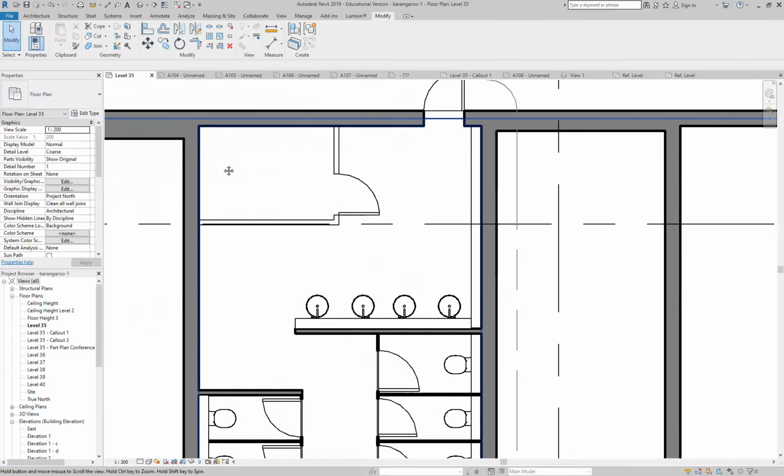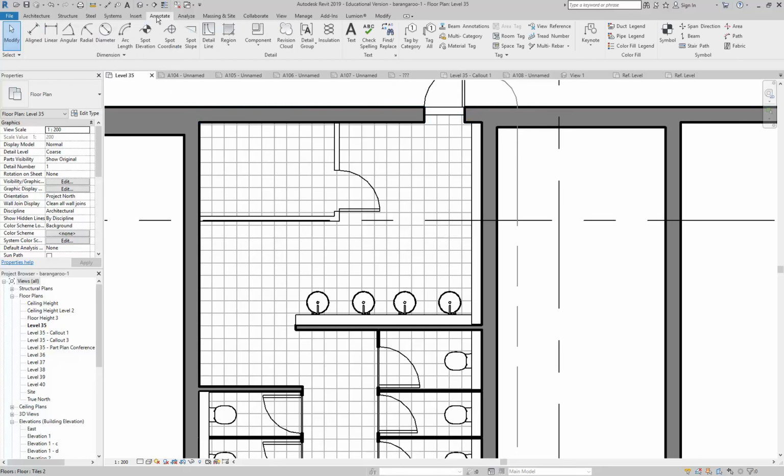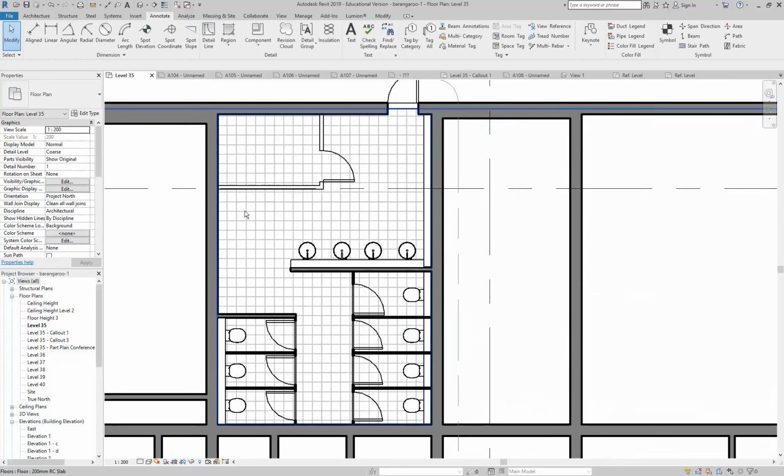I love residential, yeah. Okay, so then, just coming back to what I was going to show you, is a simple thing like a floor waste. If you want a floor waste, you've got to draw the fall, yeah, exactly. So how do you do that? Lines going to it, the direction that it falls. Exactly.